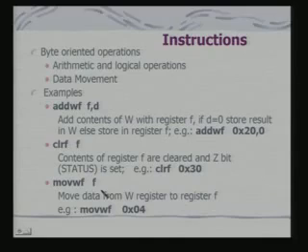Here you are moving data from W register to register F. Now interestingly, when you have to select the bank, that bank select operation you have to do prior to execution of this instruction. That means you first select the bank, and once you select the bank, then only you execute these instructions so that the correct location is accessed.